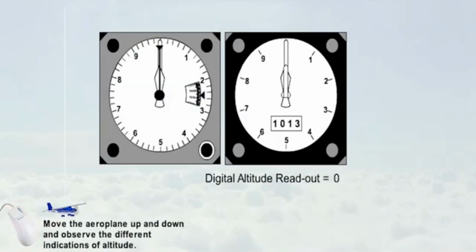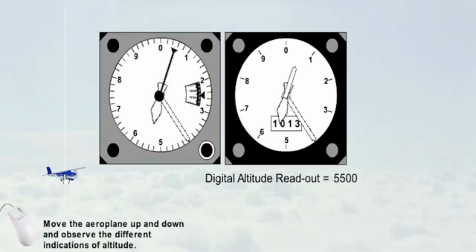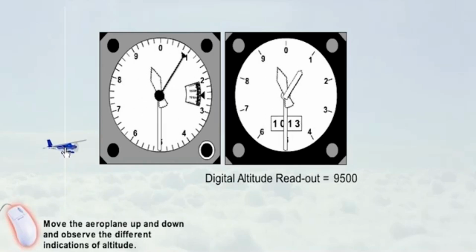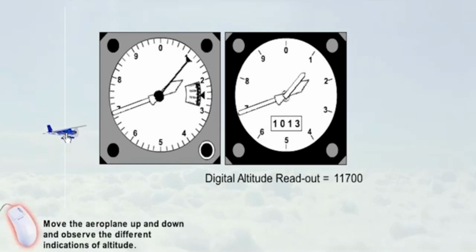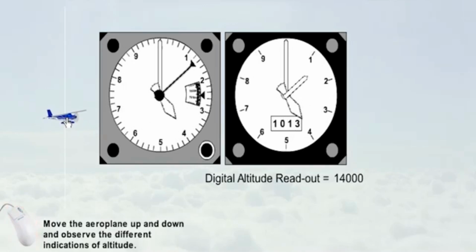The 3-pointer instruments shown here give a much more sensitive indication of height and change of height, but they do suffer from the severe disadvantage that they can be easily misread. It's not difficult for the pilot to make a reading error of 10,000 feet, particularly during a rapid descent under difficult conditions with a high workload. Accidents have occurred as a result of such misreading.